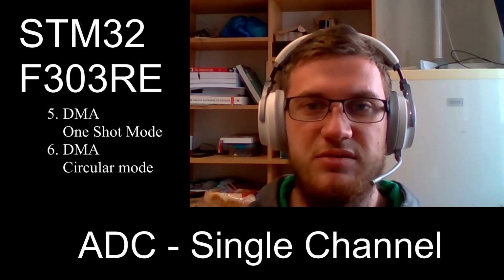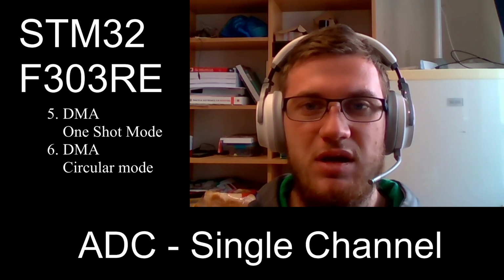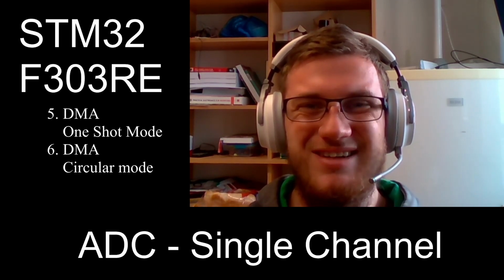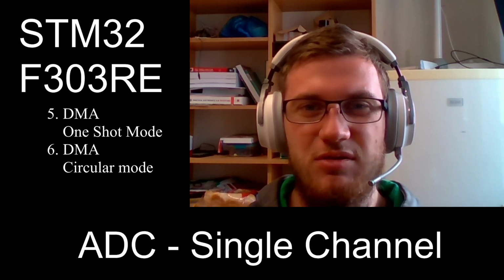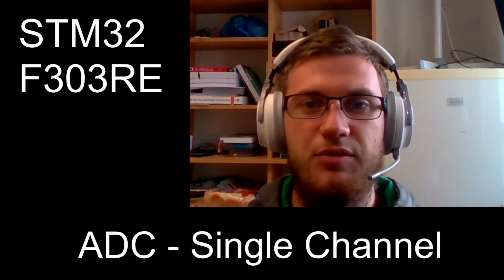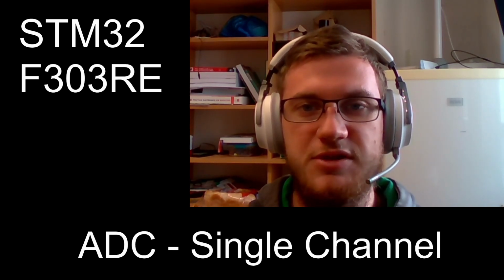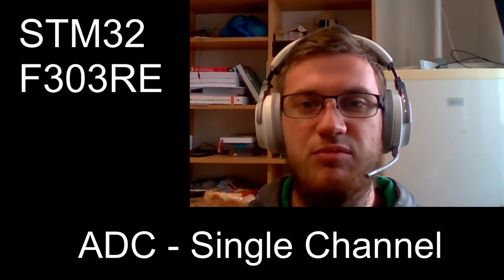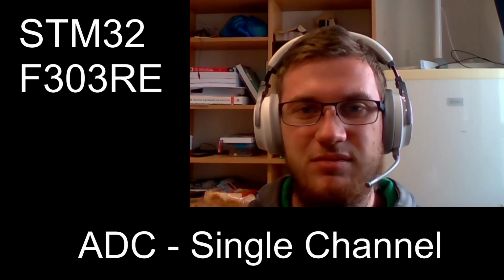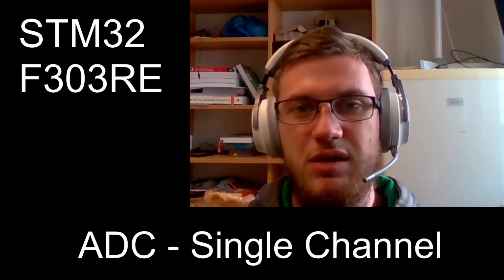The last two methods are ADC DMA one-shot mode and DMA circular mode. About DMA I will talk in later videos, so for now let's ignore these two possibilities. For every option it is possible to use single channel or multi-channel conversions, but for certain options the setup is easier and more practically acceptable. So without further delay, I will go straight to our IDE and start coding.